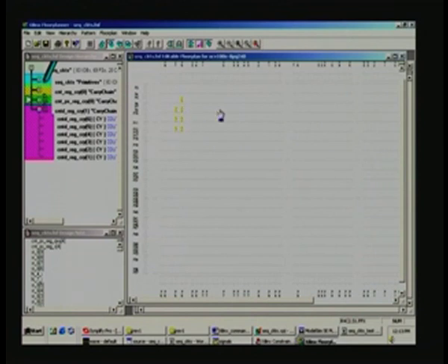And in this fashion you can reorder this placement, and then redo the pins by changing the constraints file, and then once again run starting from the Xilinx implementation, place and route onwards, then go on to the back annotation, and that would complete the entire cycle. After you do all this, you are likely to get extra speeding up of a system. That is the primary goal here in changing the pin constraints, and also changing the floor plan.